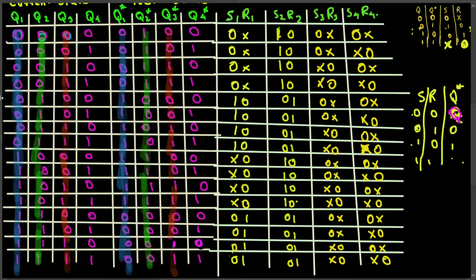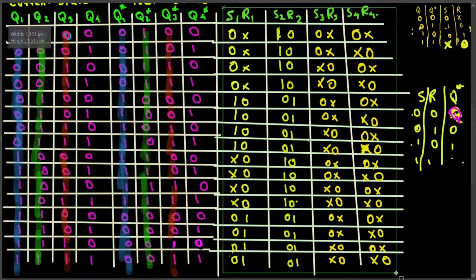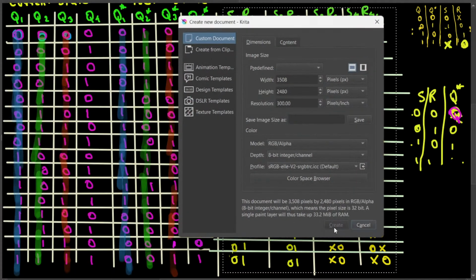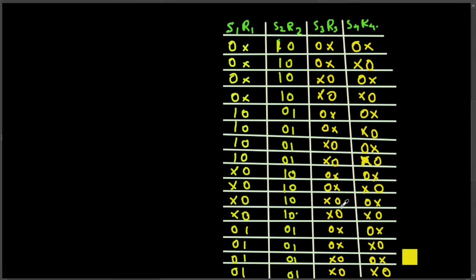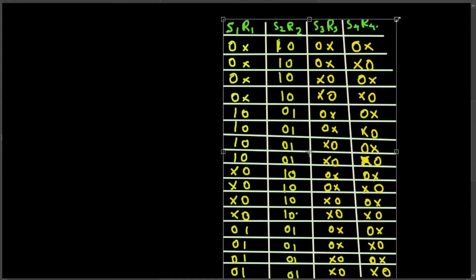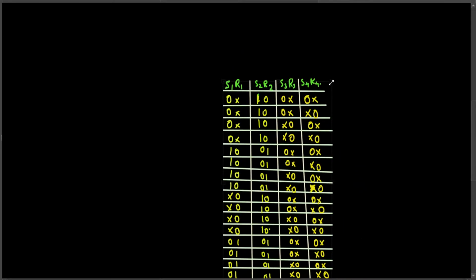We just have to create a K-map for each of them. How many K-maps are we going to have? 1 2 3 4 5 6 7 8. 8 K-maps with 16 locations each, 8 of them. Let me copy this and bring it to the next page, because here we cannot do it. Control C. Okay, I just brought the SR truth table we just derived.